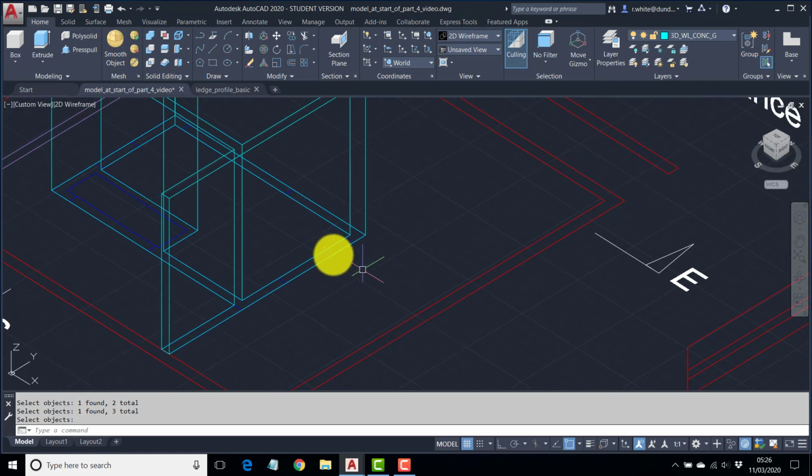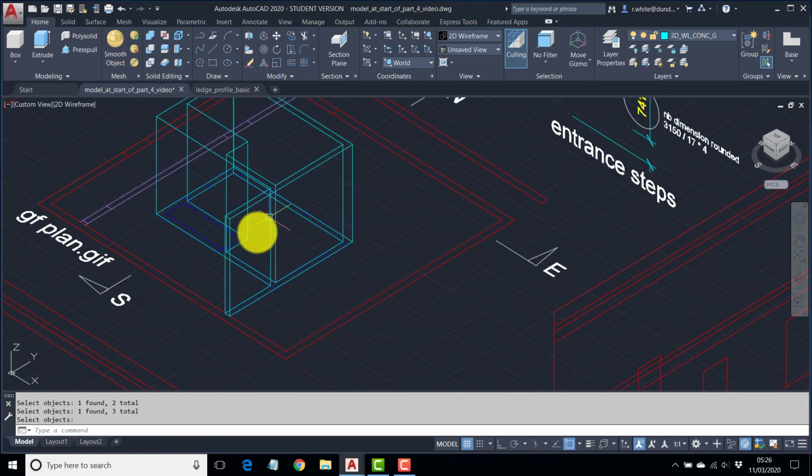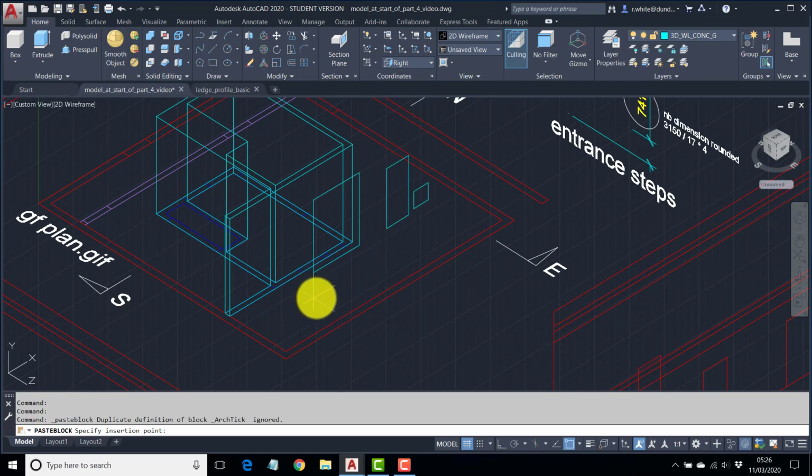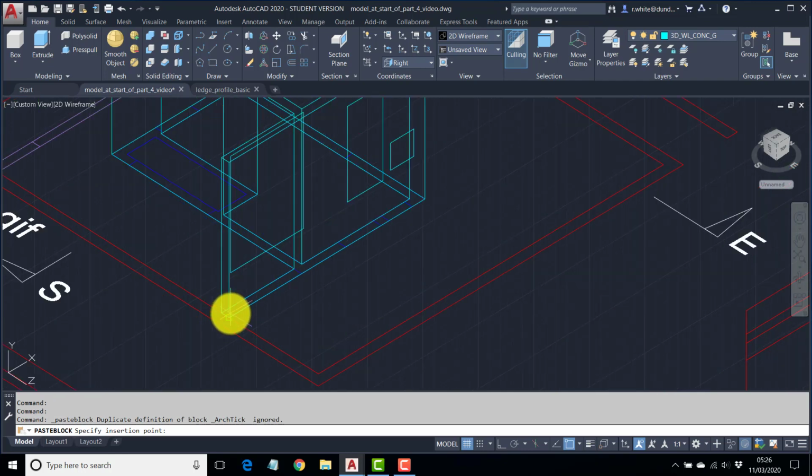We now need to go to the coordinate system that suits this wall, and if you look at the cube, this corresponds to the right view on the cube, so we choose the right UCS. Now Shift Control V, and the object should be in the same alignment as our coordinates.